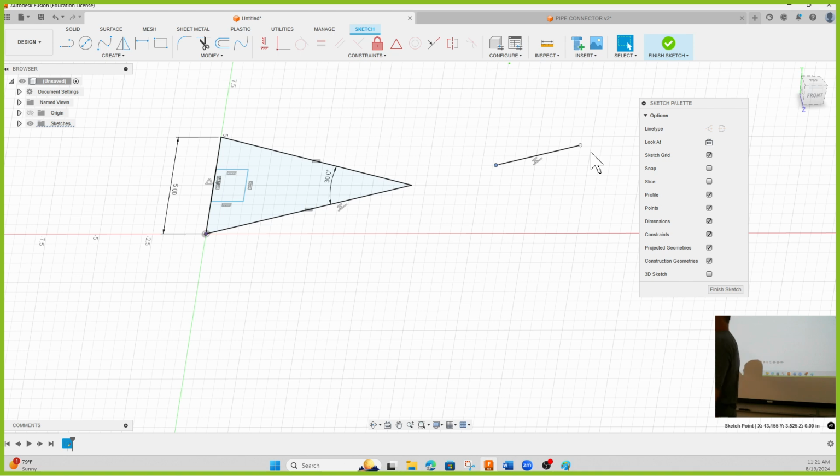So I like to keep sketches simple. When we're making parts, my rule is sketches have to be less than 8 lines total. Preferably less than 6. Preferably as few as possible. I love sketches that have 1 line on them, because I'm reusing existing geometry and I'm just adding the new thing that I want to make. 1 or 2 lines on a sketch is great. Once you get to 8 lines or arc segments or whatever, it's getting too complex. There's ways to simplify that shape. You can always simplify it. So we'll talk more about that on Friday.